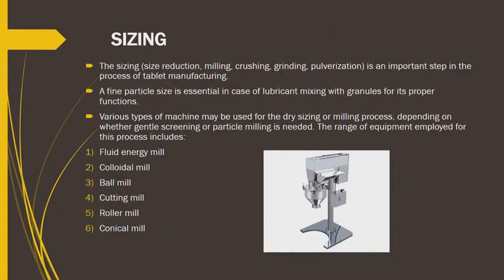The next most important topic is sizing. Sizing, size reduction, milling, crushing, grinding and pulverization is an important step in the process of tablet manufacturing. A fine particle size is essential in the case of lubricant mixing with granules for its proper functions.